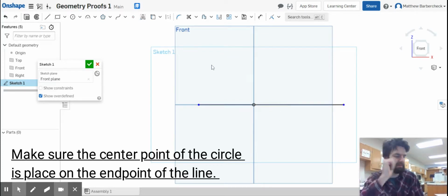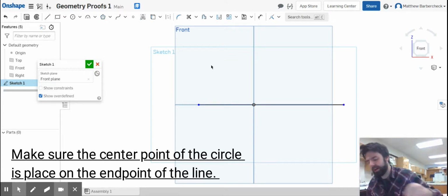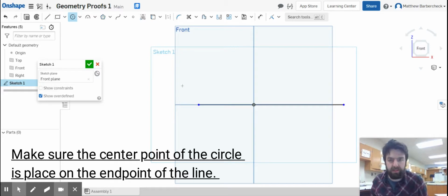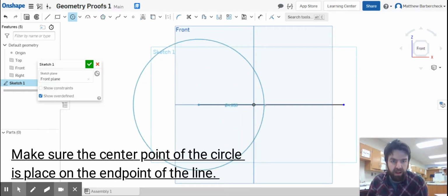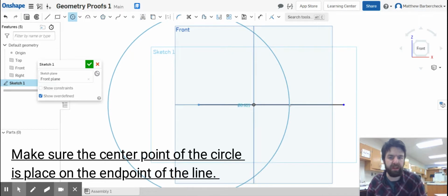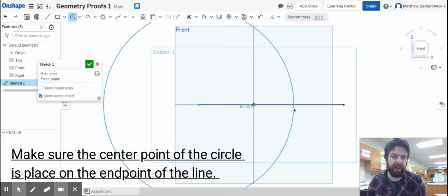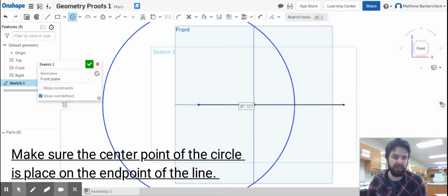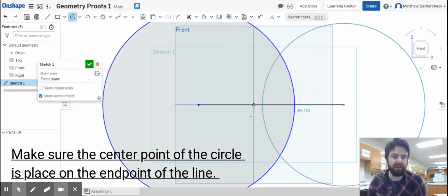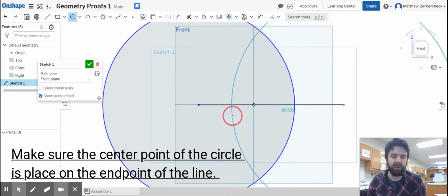But what we're going to do instead is, let's say that we're doing this with pencil and paper. We've got our line. And what I'm going to do is draw 2 equal circles at the end of the line, positioned just like so. And you want to go past the halfway point. Now, don't confuse the origin for the halfway point, but just go slightly past the halfway point. I usually try and go to the 3/4 point. Now I'm going to do the same thing over here and go to about the 3/4 point.